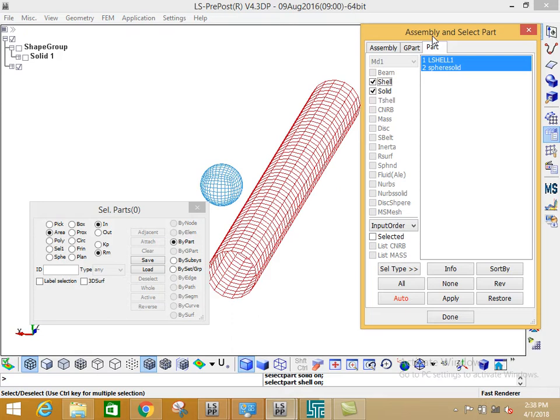Okay, beam elements. Let's say you want to analyze that beam. It's obviously 3 dimension. But if you want to make the analysis simple, you just make one beam, meaning in DYNA you have only one straight line, and you tell the software this one is actually a circular section and the diameter is 500 millimeter. This is if you want to use beam. If you want to use shell, you have to tell the software how much is the thickness.